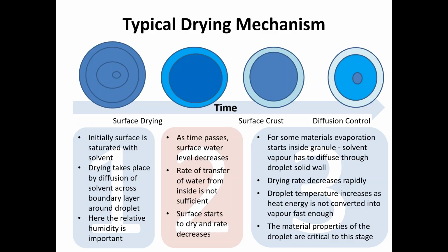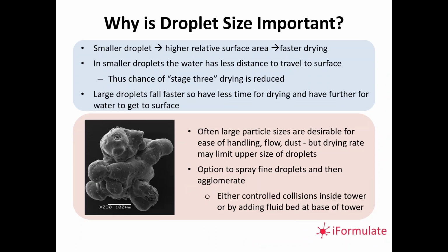Indeed, in extreme cases, the water transfer becomes so low it cannot evaporate fast enough to cool the granule down, and the heat coming in from the outside air will eventually turn the water inside to steam, and this can cause rapid expansion and puffing and high porosity, much like baking a cake, although if the formulation is too brittle, then you can get shattering as well.